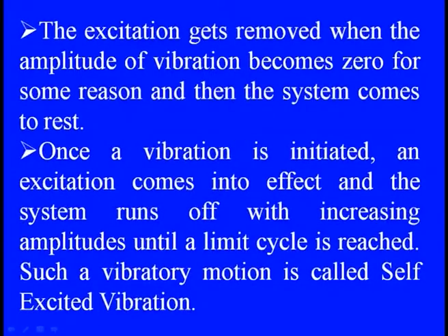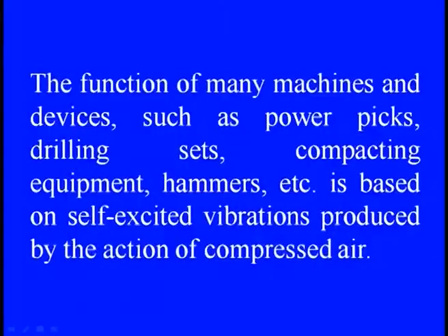Once the system is vibrating and that vibration is initiated, the excitation comes into effect and the system runs off with an increasing amplitude until the limit cycle is reached. When such vibrations happen, we can classify them as self-excited vibrations.